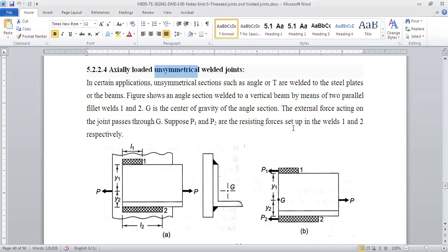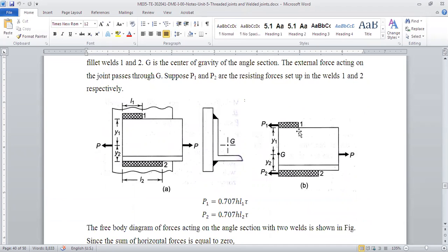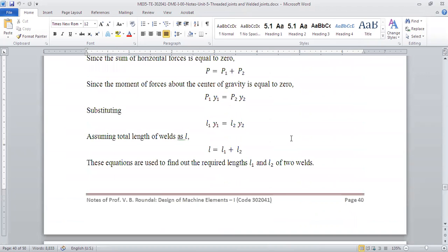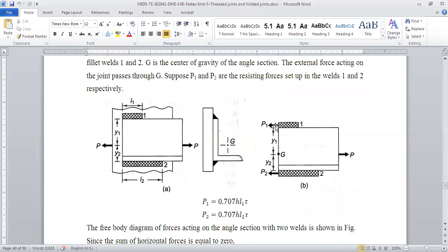Top part will go up, bottom part will come down. Where the area is minimum, the shear will be there. So obviously, there will be a primary shear in both the areas. The shear stress will be developed. And along with this shear stress, moments are also created. Now see, the load in each part will be different. If both the areas, area 1 and 2, are the same, then the load will be equal and your calculations will be much easier. We can simply calculate by using this formula.